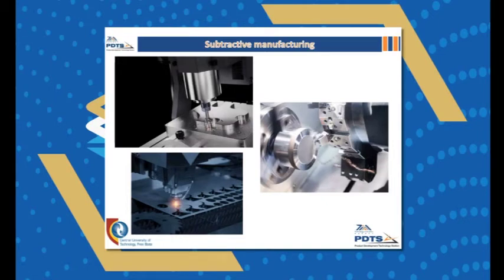The high cost of subtractive manufacturing comes in with the material. You have to buy a large amount of material to produce your parts. A large part of the cost also goes into the setup of the machine and the setup of the material when you start manufacturing. These costs can be reduced, but ultimately they are fixed. And you would have to look at other ways of producing your part.